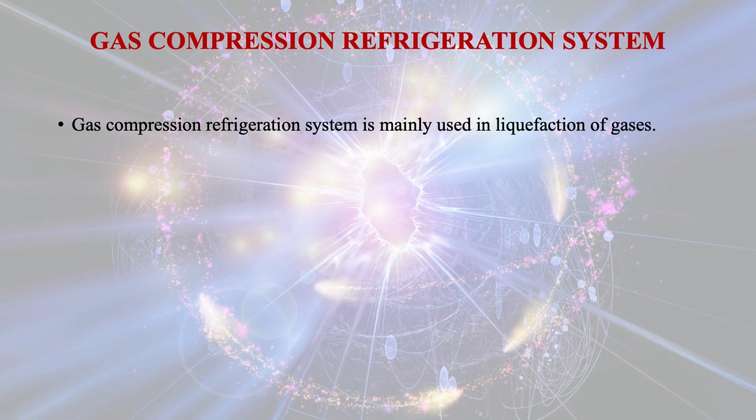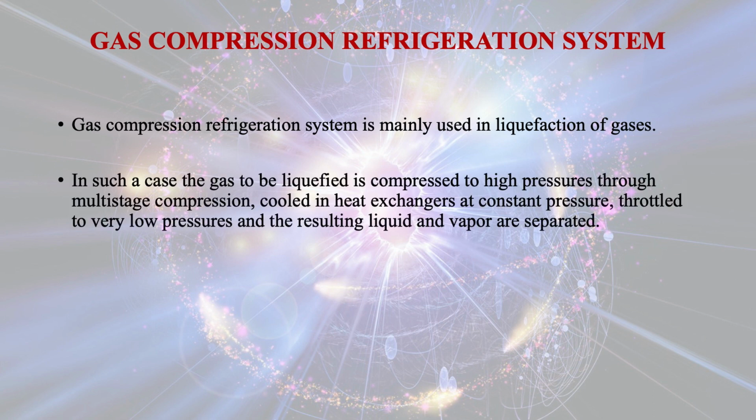Gas compression refrigeration system is mainly used in liquefaction of gases. In such a case, the gas to be liquefied is compressed to high pressure through multi-stage compression, cooled in heat exchangers at constant pressure, throttled to very low pressure, and the resulting liquid and vapor are separated.